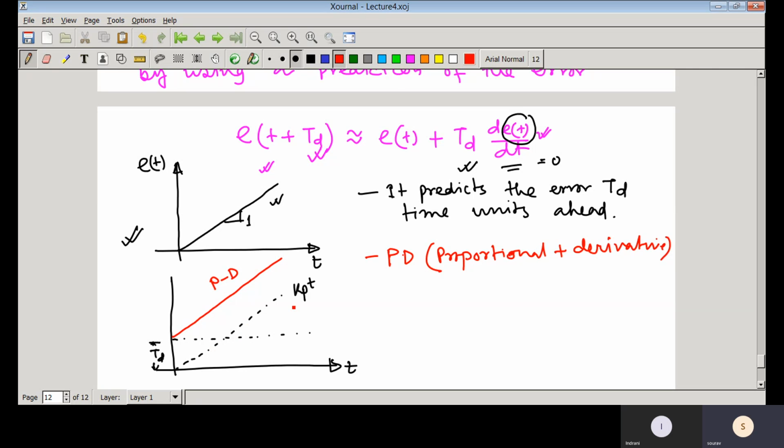I am explaining it again. So if your error signal is like this, and if you'd like to only use the proportional control, so basically the output of the proportional controller part, that means again if I draw the block diagram, say error signal is coming here, then it has two blocks, one is Kp and another one is, suppose this is Kd, or you just put here Td d by dt.